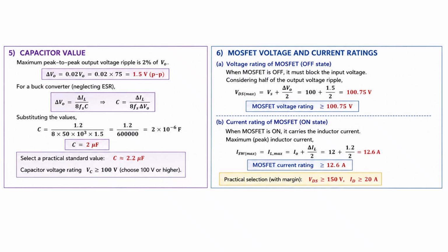So if suppose your capacitor voltage is like this, this is the maximum point. Your MOSFET voltage rating should be greater than this value of voltage. We should not consider the average voltage, because all the ratings of the devices we are using in the converter should be above the maximum rating. Otherwise, if the voltage is exceeding, your MOSFET will get damaged.